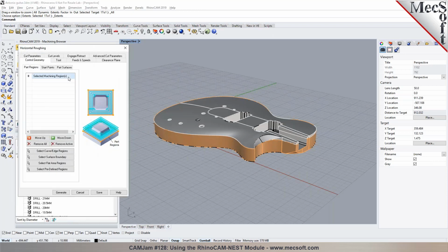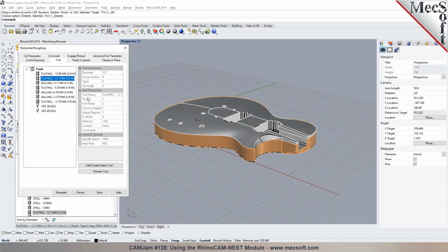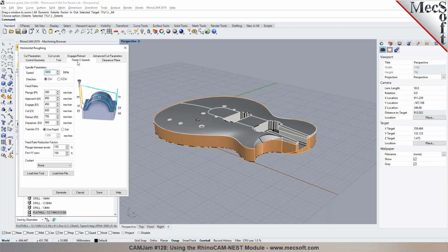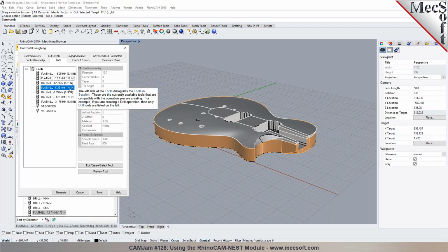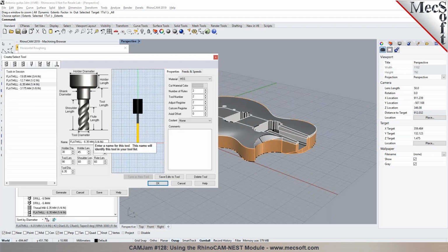The first step is to do a roughing. You pick a tool. I could say I want to use a 12 millimeter tool or a 20 millimeter tool. You can select the tool type. I have 6 millimeter or 8. Yeah, 6 millimeter, or you can change it to 8 millimeter. You can add new tools in here. You can call this, instead of 6.35, you can make it 6 millimeter.